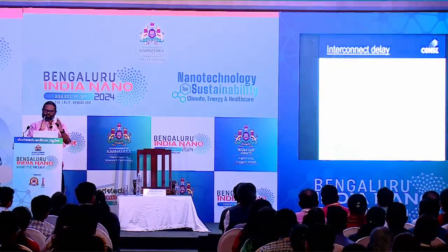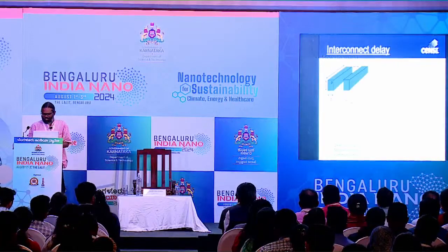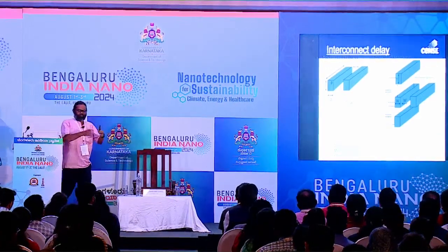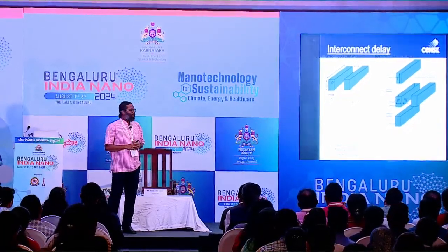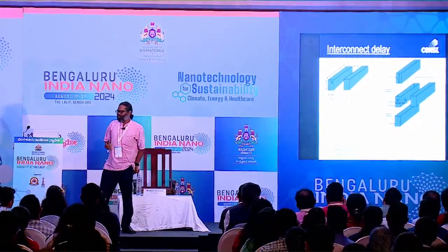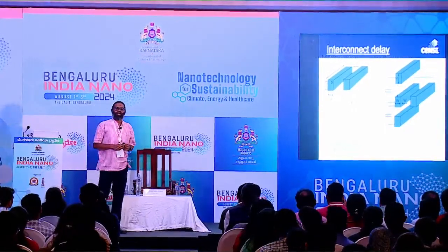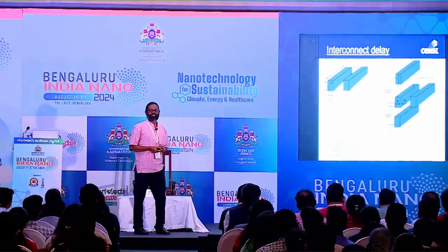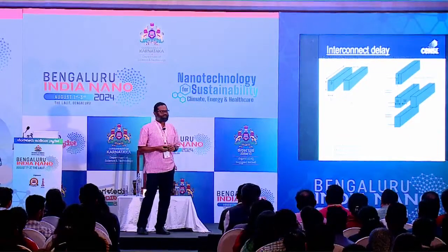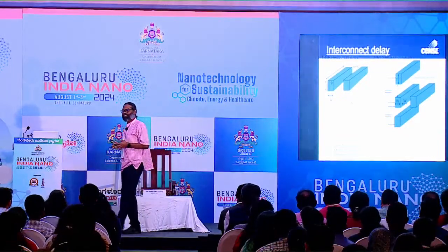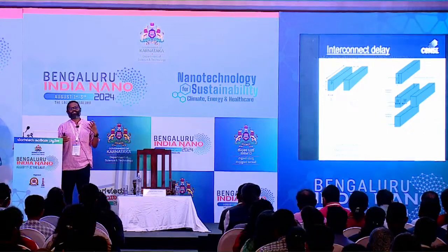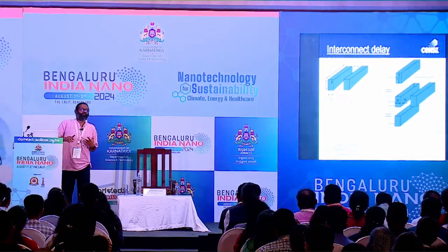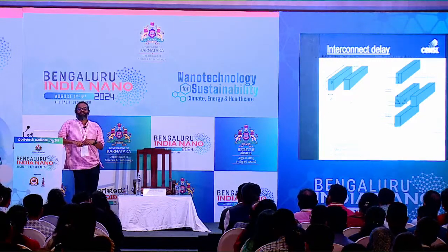But there is a challenge for some of you who are interested. If I make these metal lines on top of each other, putting them all together, then I start to get what is called the parasitics, okay? This is something that we have studied in basic electrical circuits: if there are two metal lines very close to each other, you will generate capacitance, parasitic capacitance. Why is this important? Because it is important for your laptops and your gaming system.